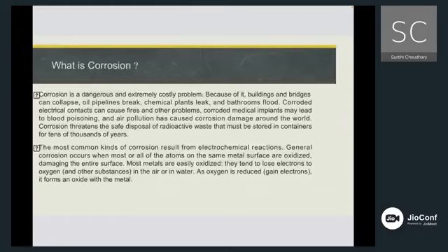Due to the effect of the corrosion, rusting takes place. Iron objects become brittle, flaky, and structurally irregular. On the other hand, corrosion is a diffusion control process. We can say that exposed surfaces are prone to the corrosion process, and attempts are made to reduce the activity of the exposed surfaces and increase a material's corrosion resistance. Processes such as passivation, chromate conversion, and certain other methods are used to protect the metal from